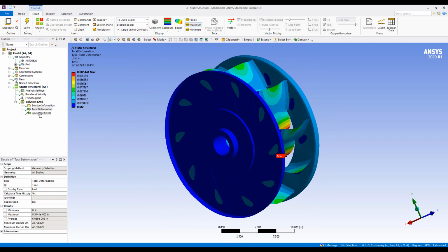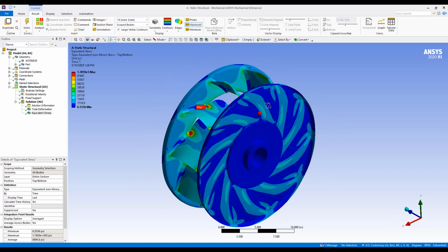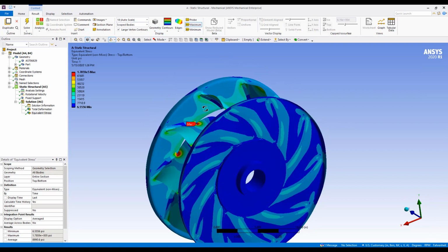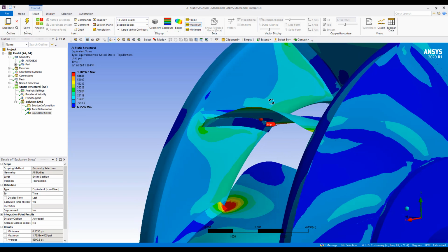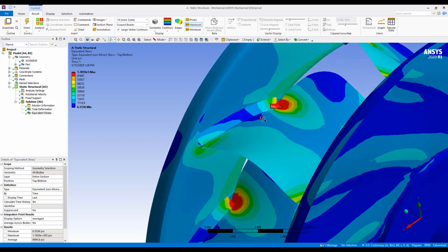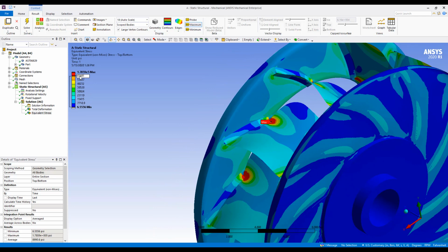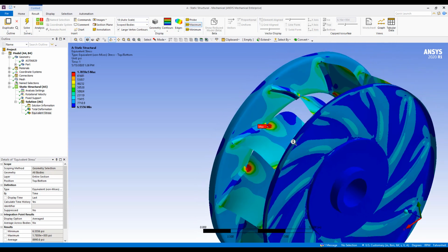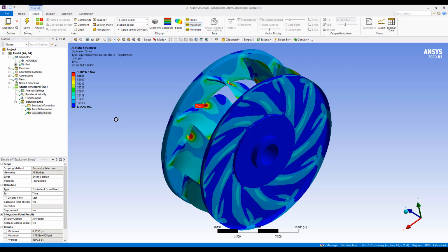Okay, if we look at the equivalent stress results, we can see the regular pattern on the flange end plates where the fillet welds are attached. And if we zoom in to these individual vanes and fillet weld groups, we can see the stress distribution. We have some stress concentrations here on this end of the weld. The scaling on the color bar, the red lower value, is set to the yield stress of this particular HSLA steel material. So these stress results, which reside in the Ansys Mechanical .rst file, are going to be brought into Ansys nCode DesignLife, and they'll be used in the fatigue analysis.